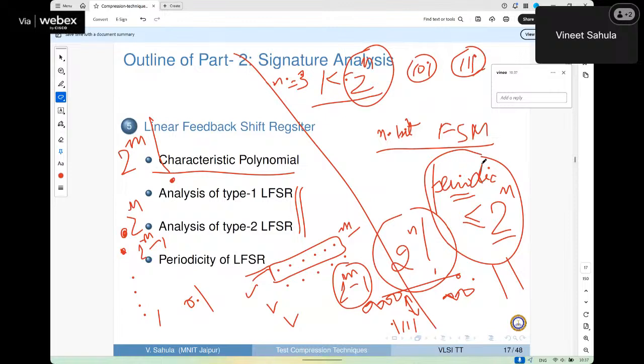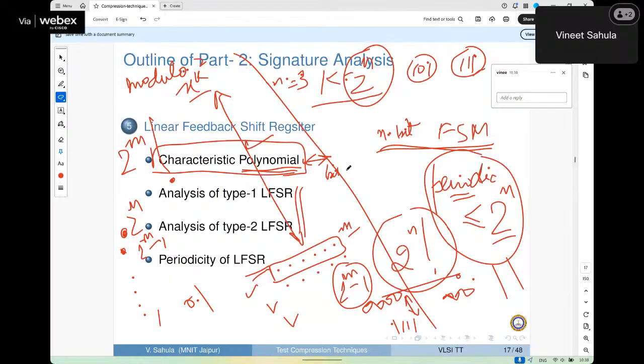One more characteristic also. So we have discussed something here that we have to design the LFSR. It has a period. Then we can correlate that with a polynomial. Very fantastic correlation. If you have modulo 2 arithmetic and you have a polynomial in x, power of x, then we have a perfect matching with bit patterns and a polynomial. What I'm saying is, a polynomial will have a perfect matching equivalence with a bit pattern of the same width, an m bit pattern.